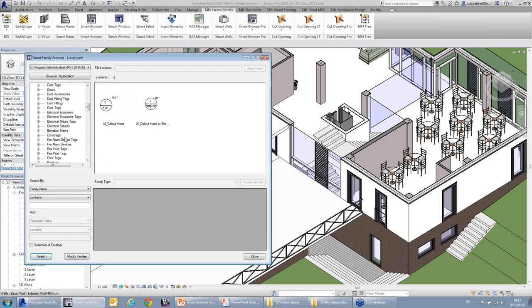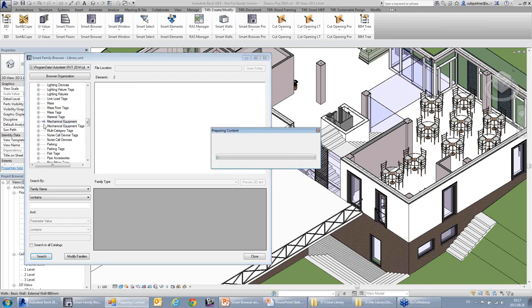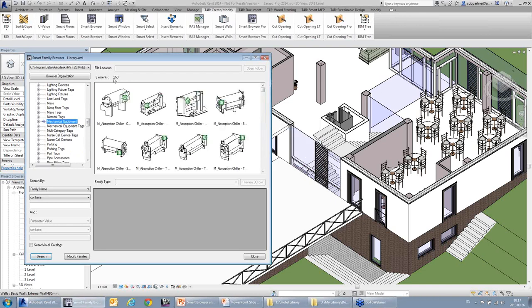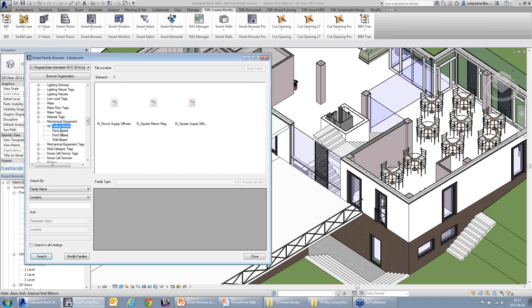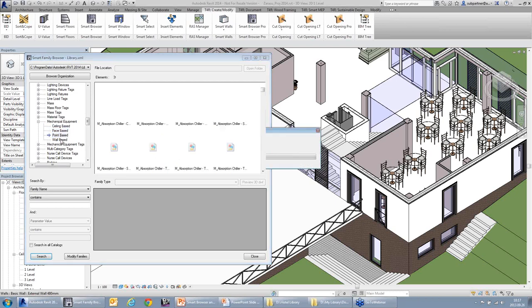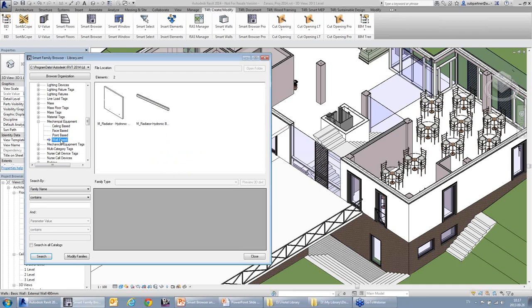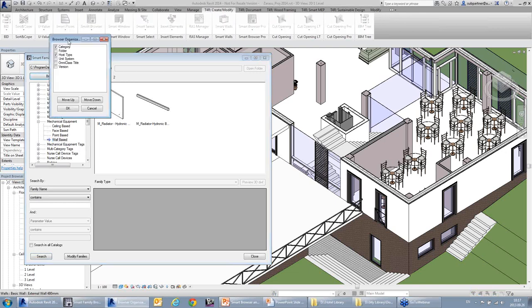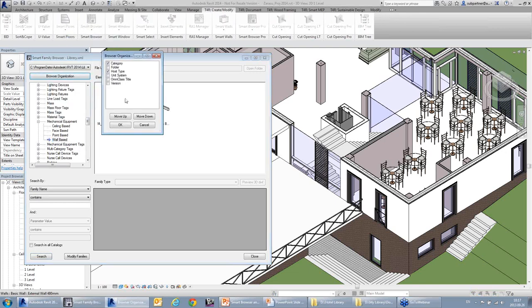And right now, if we go into our category with the name mechanical equipments, we can find them all, 250, and then we can expand them and filter those ceiling-based or face-based or point-based or wall-based families. So it will be very handy to understand what is the host of the families.